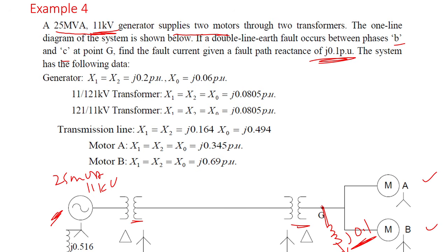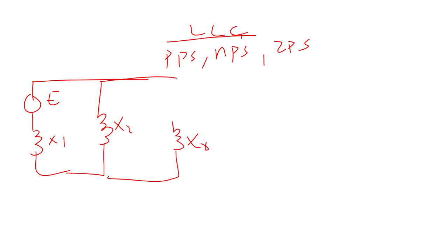But in case the fault has a resistance or reactance to ground, like this example, where the fault path itself has a reactance XF, I would have to bring in 3 times XF. If it was a resistance, it would have been 3R. It needs to be inserted where the zero phase sequence is. That's when you need to know the fault has a reactance. So note that. We just need to know from the power system what X1, X2, and X0 are. Good. Now let's find that.